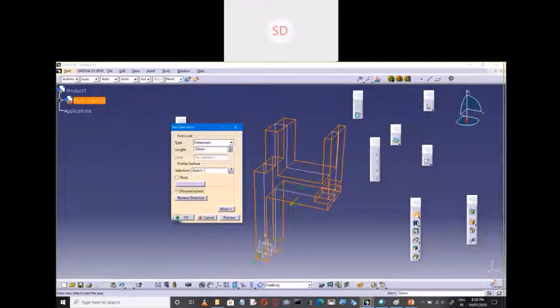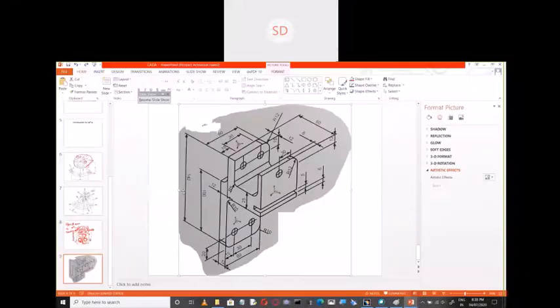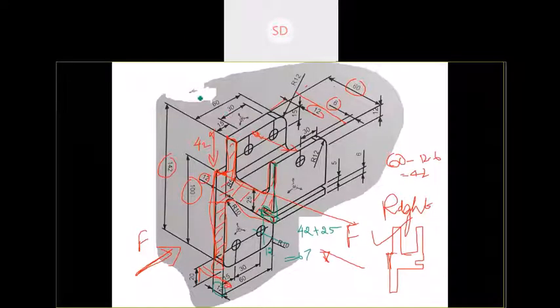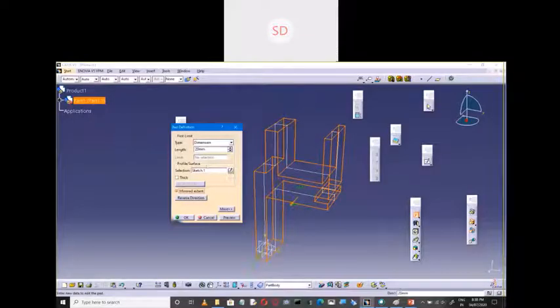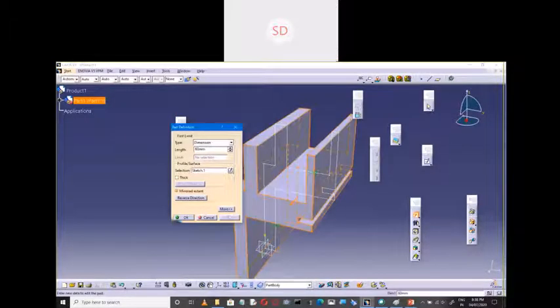Now you go for a mirror extent. Check out what is the total depth here. Now total depth of component is 60. Now what I have done, I have selected mirror extent here. Mirror extent means from the drawn profile, back side it has to extrude 30 mm. Front side also it has to extrude 30 mm. Now I'll provide the length as 60. Preview, okay, preview.